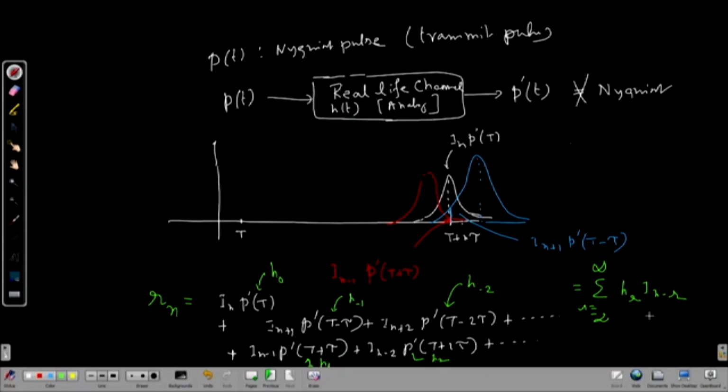Future symbols are coming, but do not worry, this is not real life in the sense of how causality is bridged here. Causality is bridged because when I sample the current waveform to find out In, by that time I have already triggered the future waveforms. So they pass through the sampling point, and at the sampling point they already exist, so they contribute with their values.